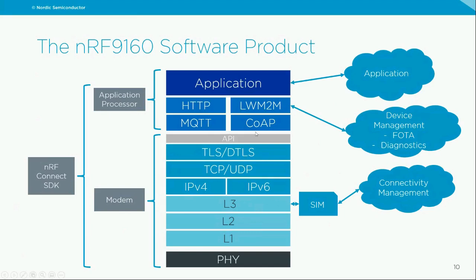When you then look at the application side and the application processor, everything inside the SDK is open source. And here we have all the key protocol stack and middleware that you need for connection. And we have complete application examples that show you how to connect to the cloud using CoAP, lightweight machine-to-machine, HTTP or MQTT, show you how to do device management, how to do application FOTA, and how to do modem FOTA, and so on.